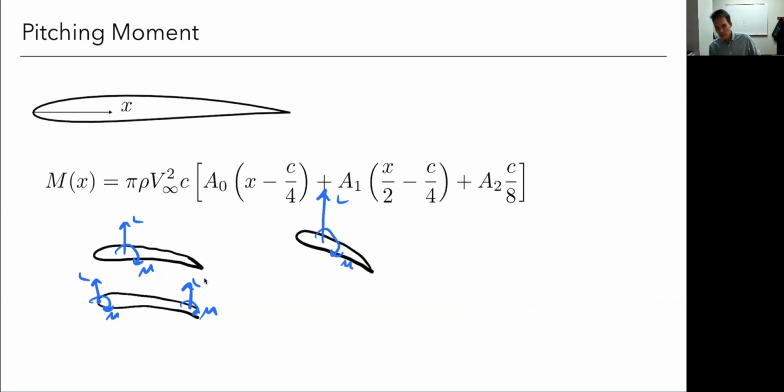And so I don't really like that, because then I can't say, here's the center of pressure of my aircraft. You say, well, what's the angle of attack? And when I change the angle of attack, which I do a lot, I have to keep moving the center of pressure around. Well, there's a different concept, which is called the aerodynamic center. The aerodynamic center is the point on the airfoil, not where the moment is 0, but where the moment doesn't change. So the moment is independent of angle of attack. In other words, dM/d alpha is 0. The moment is not a function of angle of attack.